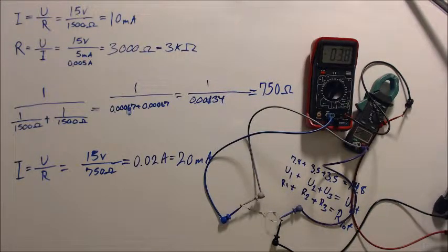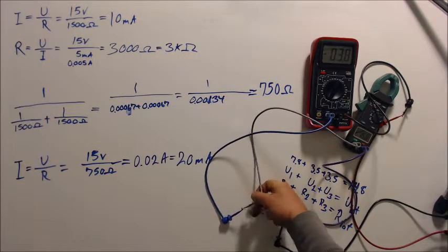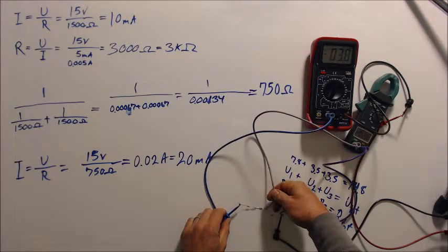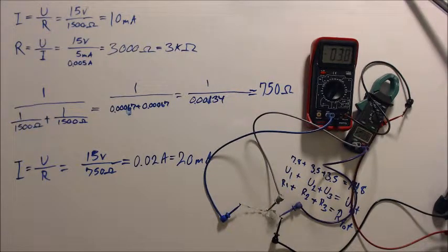What I want to show you here is how the voltage is being divided. We remember from the voltage dividing that the biggest voltage drop will be over the biggest resistor, because in our previous example from the serial connection, we remember that half the voltage was dropped on R1, which was a 3.3 kilo ohm resistor. So let's see what the voltage drop is over a parallel connection here. Well, that's only 3 volts.